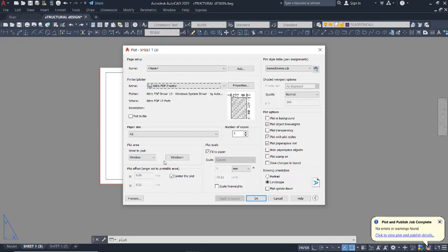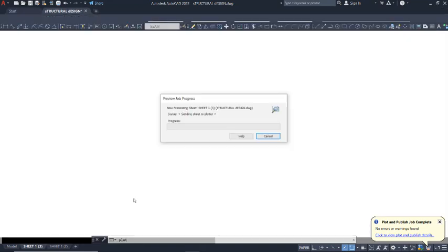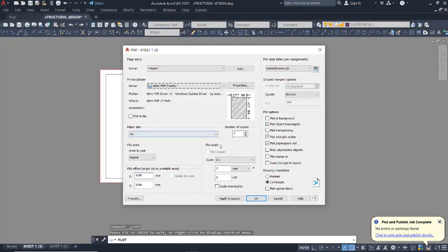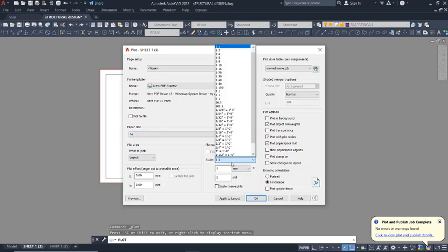All right, you can either use layout. You can use layout, and then you can preview what you have on the layout. So if you preview what you have on the layout, this is what you are going to see. The reason is because of the scale, so you have to exit that. So you can see over here we have scale 1:1. So it is fine, use the same scale that you used over there, which is about 1:30 or 1:40 scale that was used successfully.